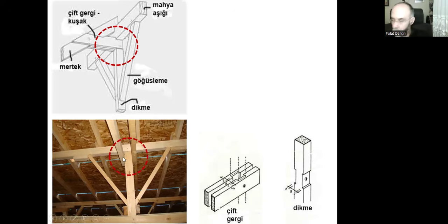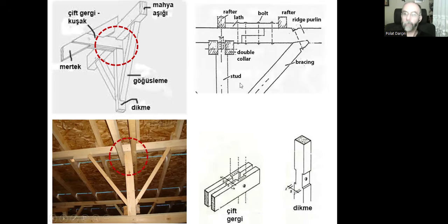They are just nailed like that. And the same logic applies for the connection of bracings and ridge purlin. We can connect the stud like that to the ridge purlin. If you have this connection right under the purlin and the stud, it will hold in a better way.